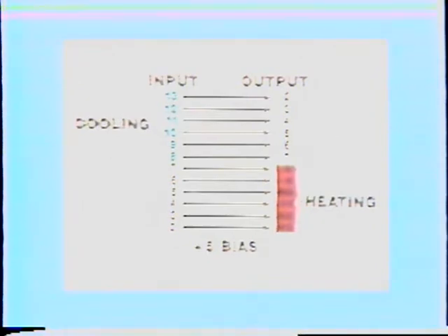A drop in thermostat branch line pressure will increase the output of the reversing relay to open the steam valve, or an increase in the thermostat branch pressure will open the chilled water valve only after the steam valve has been closed.